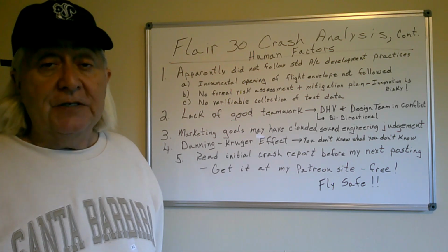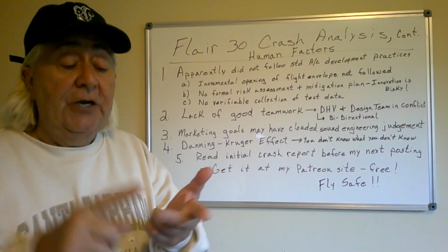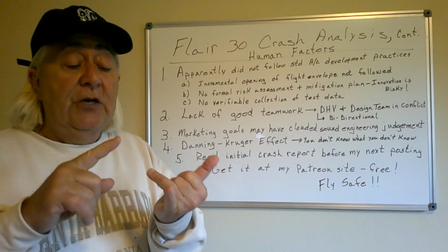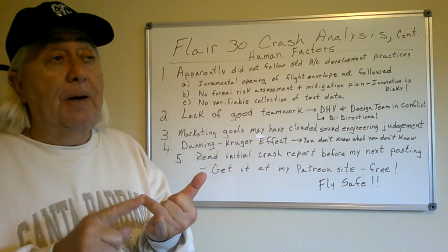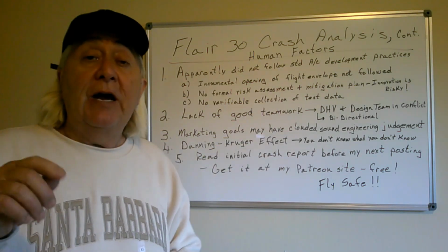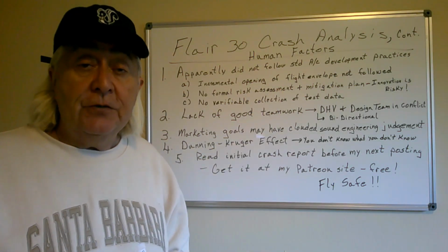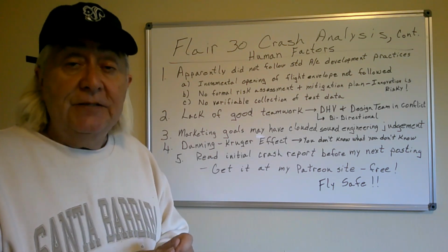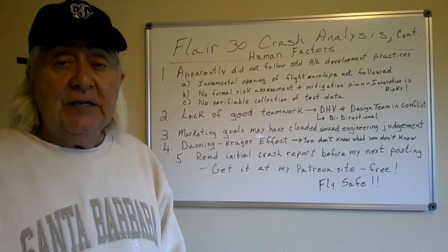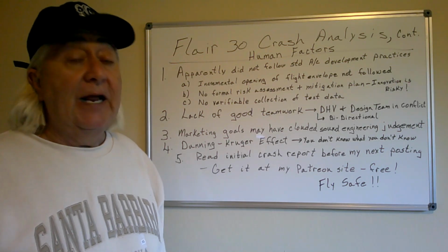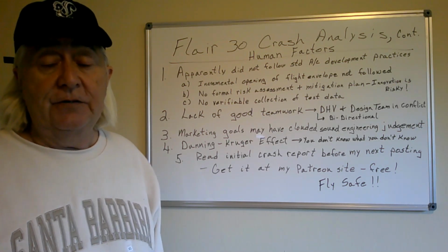And there's a whole bunch of this that you go through. You got to test the speed range. You got to test your roll rates. You have to test your pitch rates. You have to test coordinated turns at different banks. You have to test the full range of control surface deflections. And you have to combine those with different speeds. So you get this matrix that's large. A lot of data points that you have to check. And it takes hours and hours and hours of flying to do that.